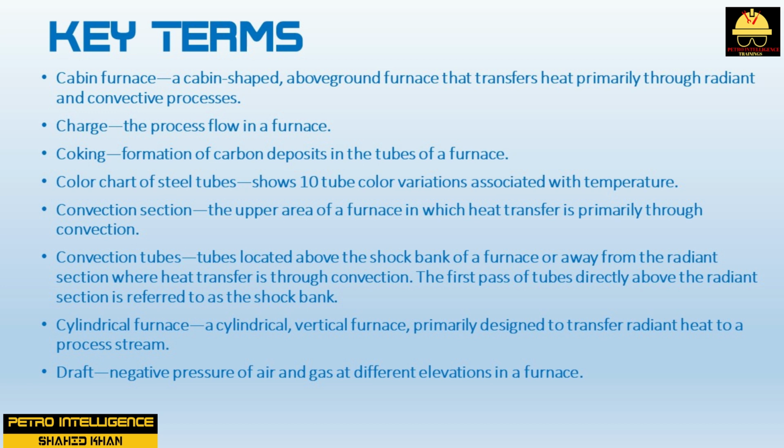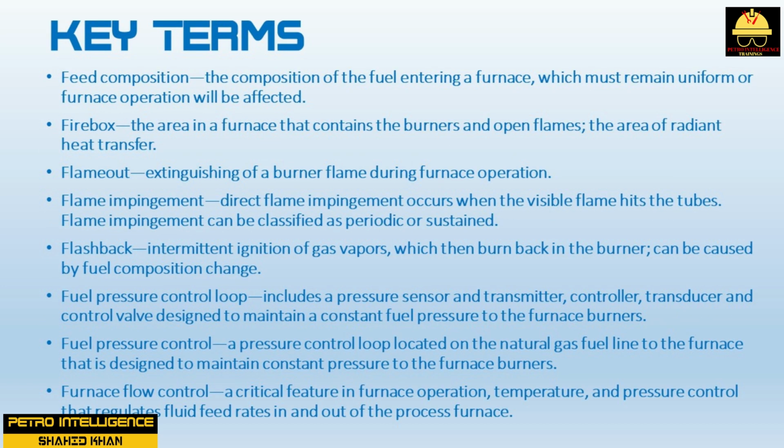Cylindrical furnace is a cylindrical, vertical furnace, primarily designed to transfer radiant heat to a process stream. Draft is negative pressure of air and gas at different elevations in a furnace. Feed composition is the composition of the fuel entering a furnace, which must remain uniform, or furnace operation will be affected. Firebox is the area in a furnace that contains the burners and open flames, the area of radiant heat transfer.